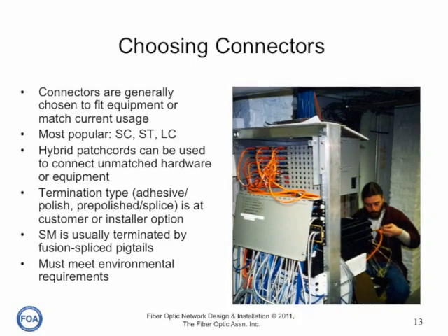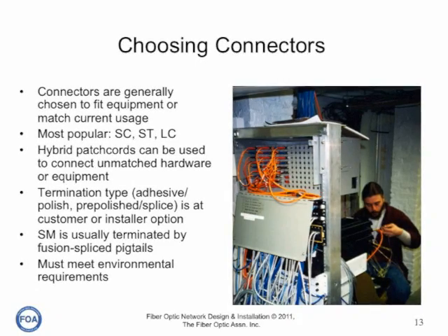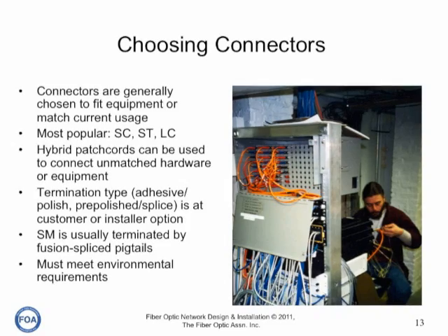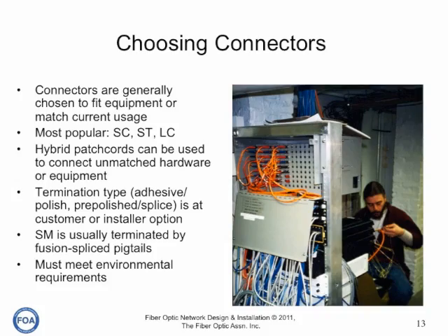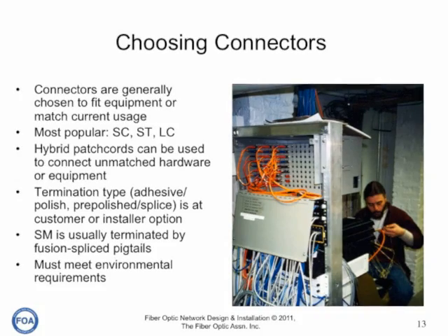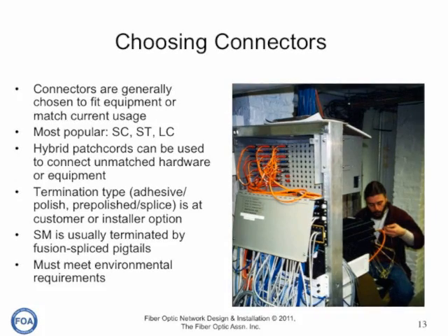The termination type, adhesive polish, pre-polished splice, is at the customer option. And single mode, of course, like the outside plant, is usually terminated by fusion spliced pigtails.